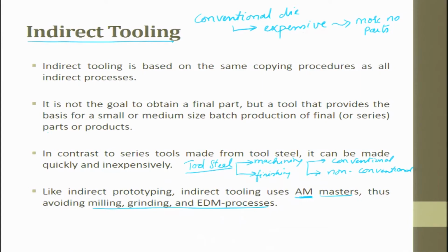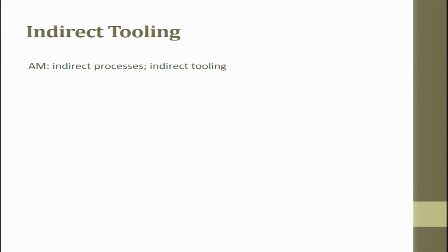So, if you decide to make a metal die, the route itself takes 6 months, and it is not necessary that after 6 months whatever you make gets accepted by the customer. Though modular designs can be followed, finally the shape, size and inserts have to be properly planned, which takes a long time. But if you follow the additive manufacturing route, that can be achieved very fast and we look for outputs.